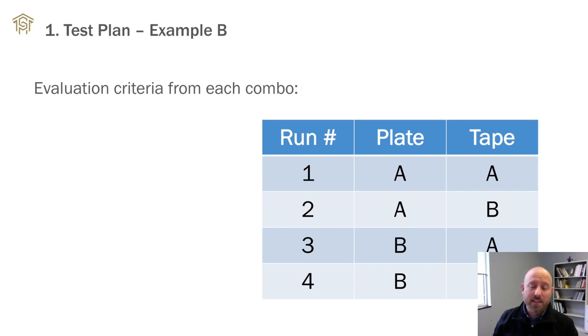Now that sounds like a lot for us, but let's say you're trying to get set up for a press run that's going to make tens of thousands of dollars, that's just a drop in the bucket to make that happen, okay? Just something to understand. The way that we're going to evaluate this is for opacity. How opaque is that white ink printing? The weight. Basically, what's the weight of the ink that's being laid down? We're going to do a visual inspection of it. How clean, how smooth is that ink laying down?